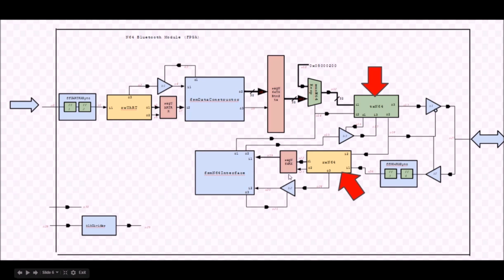I was also able to integrate my own open collector output and input hardware here to implement the bidirectional nature of the protocol. And in parallel to all that, I have a UART module running here. Now, since I only took up 1/10 of the space on the FPGA with this design, I can simply copy this entire hardware for the rest of the 4 controllers. So now that I have those afterthoughts out of the way, let's get back to the oscilloscope.